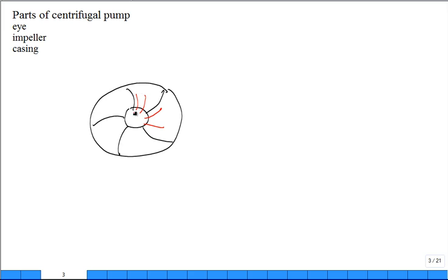The impellers cut into the eye region, and they sling it off the tips. So if you look at a velocity diagram of the tip, its tangential speed is high. The fluid is coming off, sliding along the vane, right? Coming off like this. So that's two vectors. You put them together to get the actual fluid velocity by a velocity diagram. So it's coming off really fast.